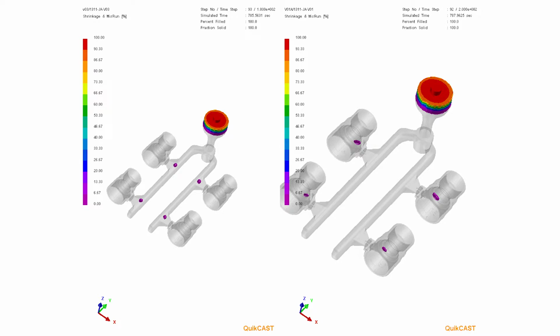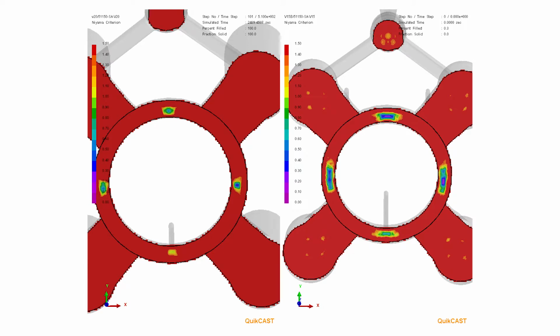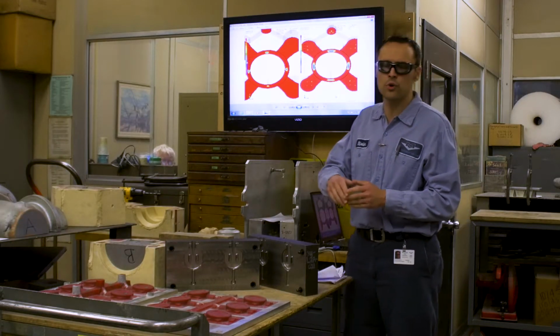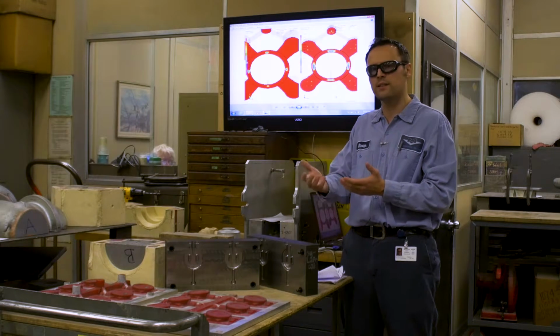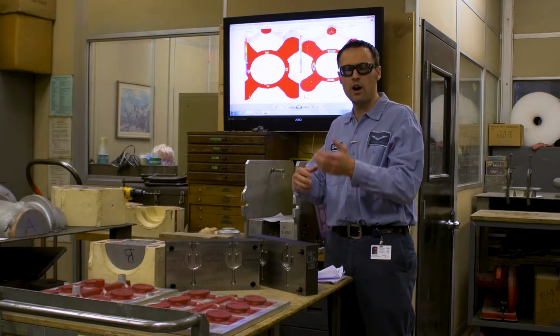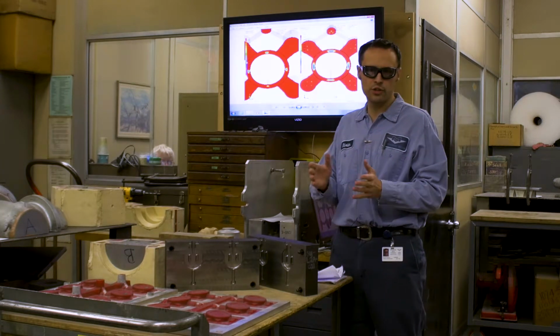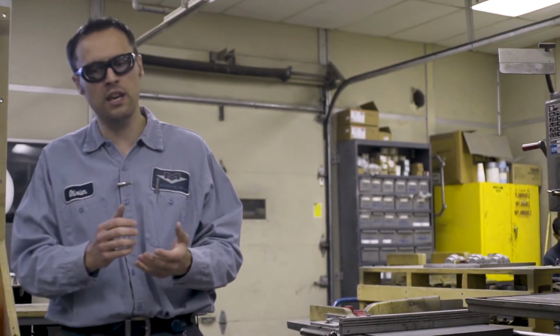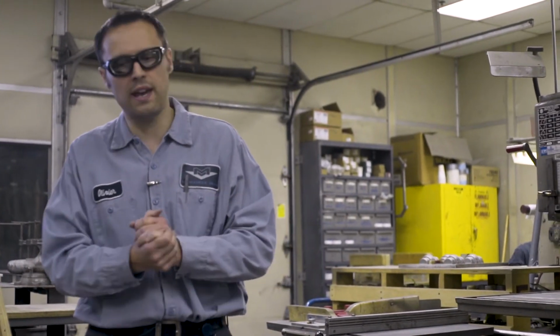Other things we look at as a common defect for us in the valve business is microporosity. Here we pressure test all of our valves, and we also pressure test most of the components that go into the valve. And sometimes you have a casting that's machined and it looks great, and you pressure test it and it's leaking, or there's a little water weeping when you pull it off the test fixture, and that's not good. You look at it with your naked eye and you cannot see anything, but you have that water weeping out, and that's due to microporosity in a lot of cases.